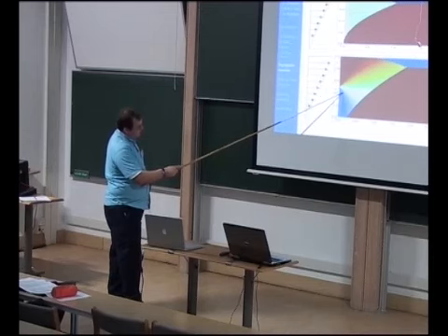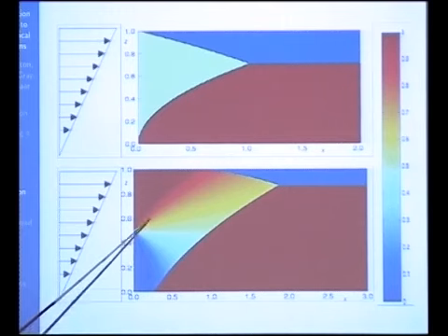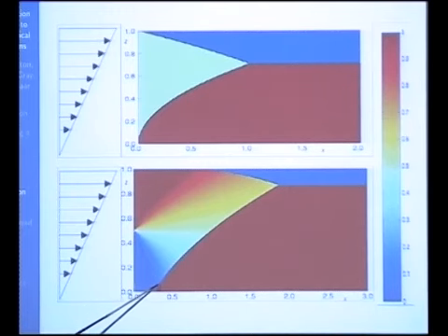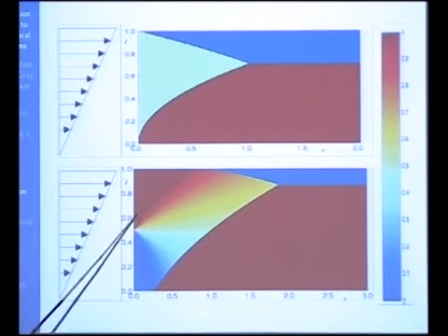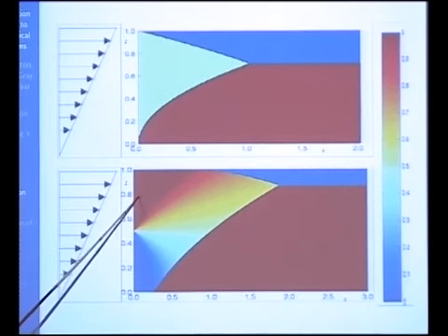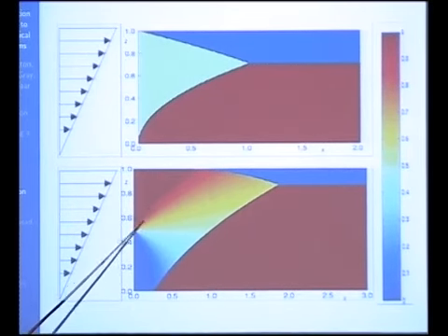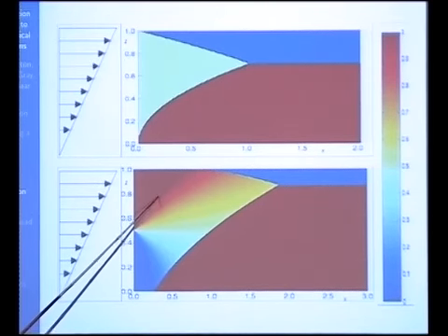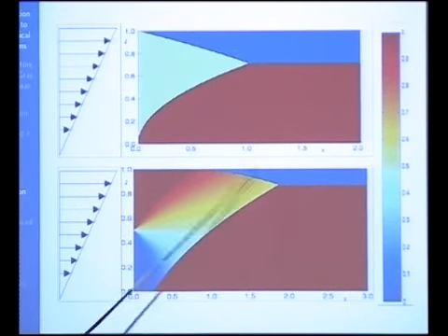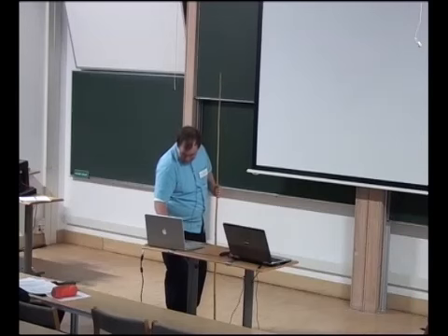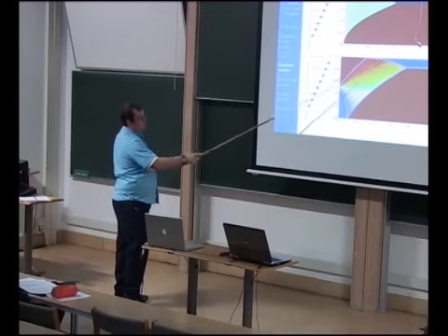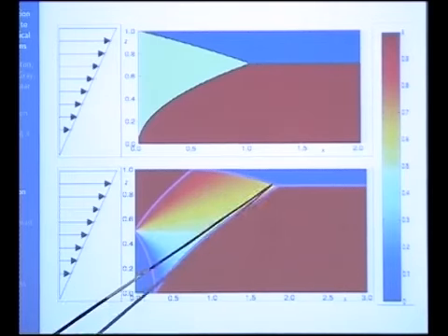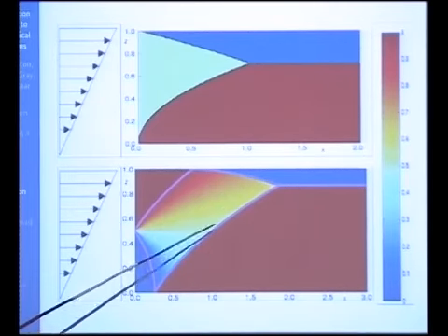So here you place the small particles on top of the large, and you get this much more complicated structure. Basically, this line here represents the first small particle percolating downwards through the layer of large material below it, pushing the large material up, and eventually this small particle reaches the base where it's perfectly happy and travels along. And then here you've got small particles traveling along which are perfectly happy, but as they come across large material which has been driven up by the small particles before, they start to travel down and they cross this shock there.